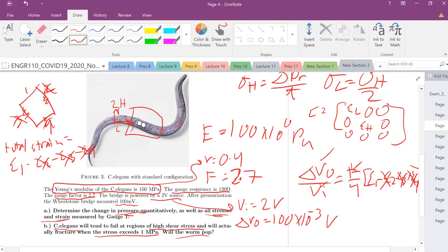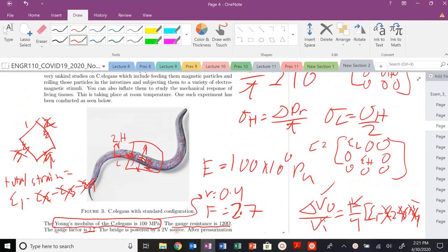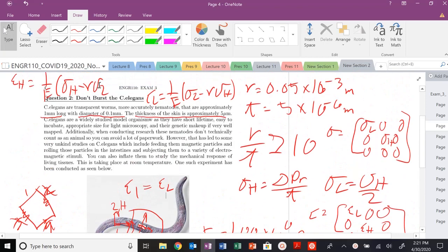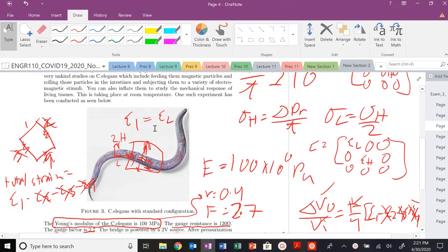Well, again, we're looking at what's going to happen to the wires. We're going to elongate, so the strain in 1 is going to be epsilon, the strain in the longitudinal direction. And you see that up here, because we only have this quarter bridge, you can see that compression in your hoop stress will pull these up, and that's going to lead to some Poisson's ratio of contraction. That's already encapsulated in your epsilon sub L here. So that's all we're going to deal with, this epsilon sub L and this epsilon sub 1 for this particular stress state.